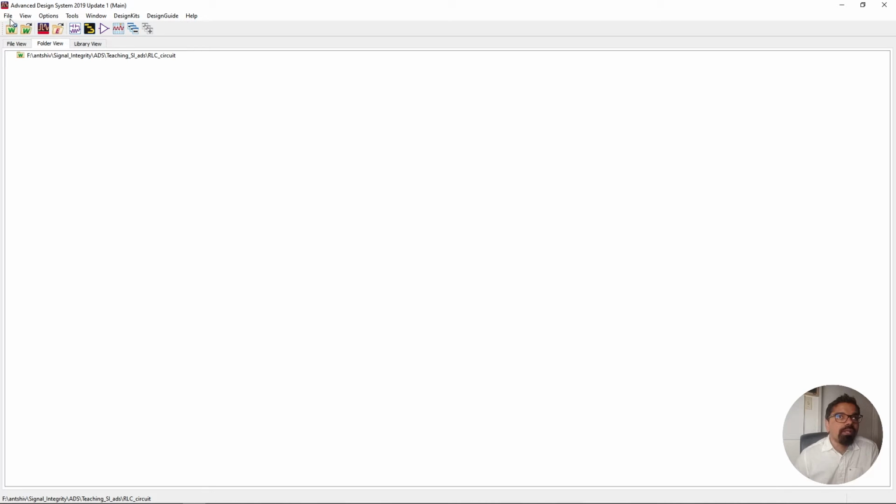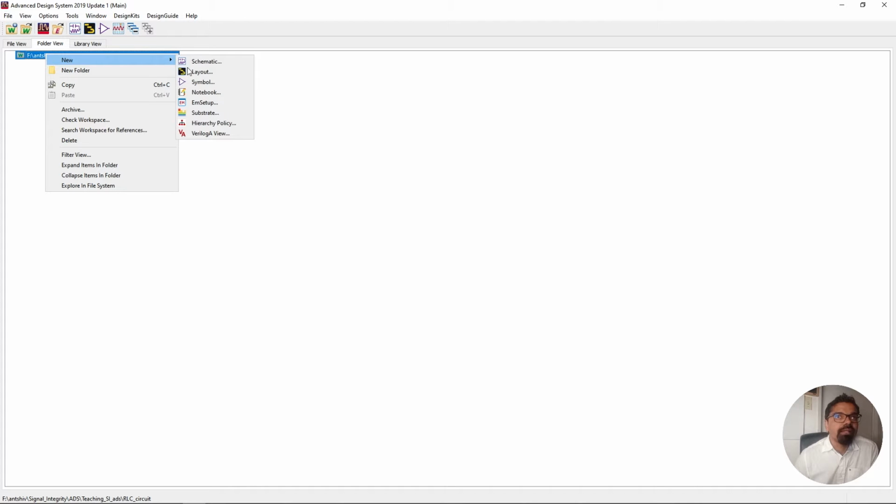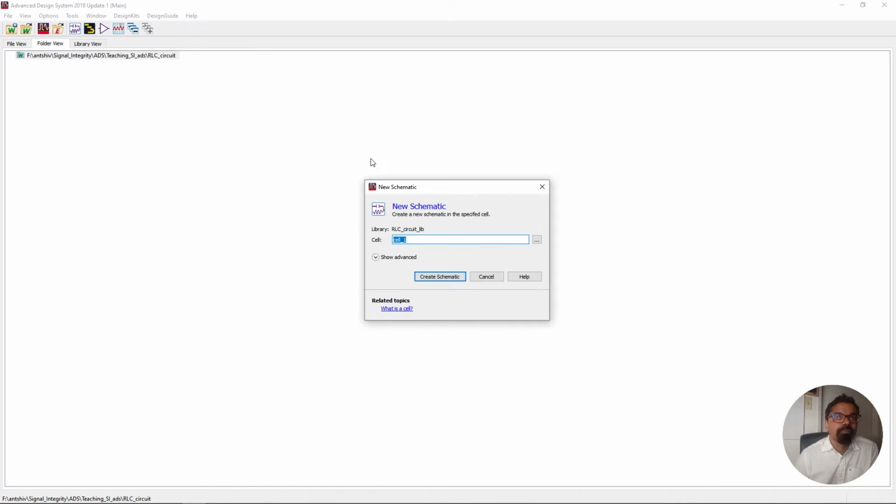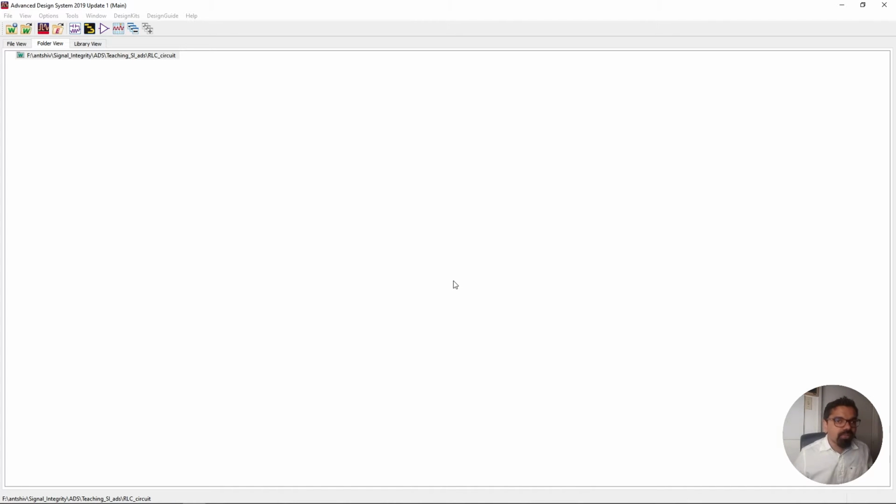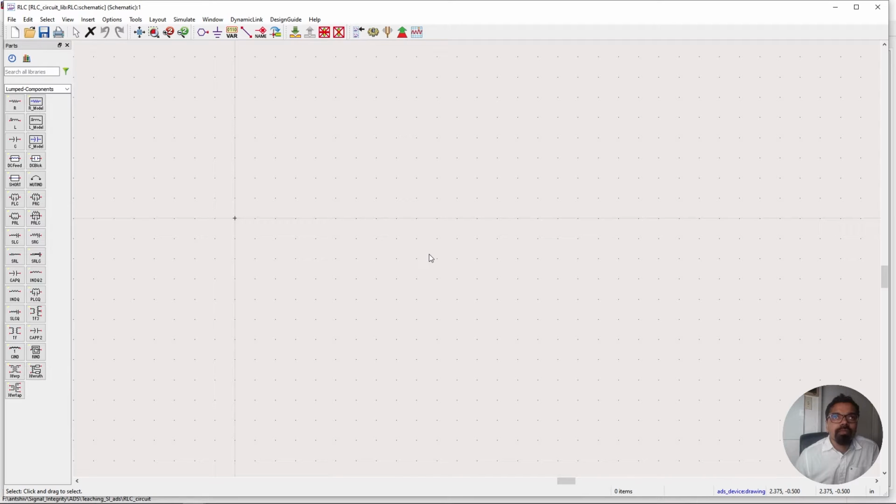And from here, what we can do is create a new cell, a new schematic. And a schematic is based on certain cells. In this particular case, I'm just going to put here, say, RLC. It's very similar to what I did in the previous video. But in this video, I'm just going to go step by step as to how I made those circuits in the previous video. Once you click on schematic, you'll be greeted with this particular window.